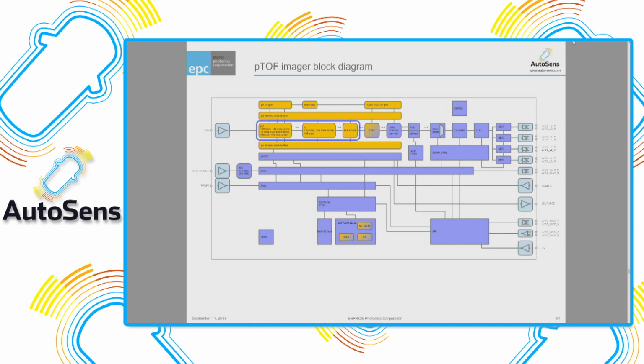That's the block diagram of the imager we implemented. Basically, this is the pixel field with the conveyor belt, readout circuitry, fast ADC, and then some LVDS channels. This imager is running extremely fast. The CCD can run up to 250 megahertz, sampling in 4 nanosecond slices. There are 48 row ADCs in parallel, sampling 3 rows each. So the total number of rows here is 144, and 256 columns.